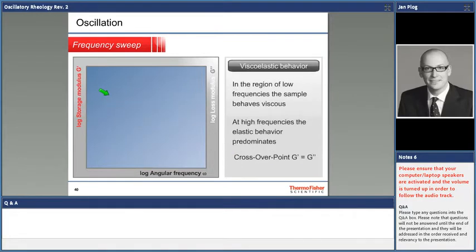However, those were the two extremes. Let's have a look at viscoelastic response. Okay, and here you see what I was talking about earlier when we talked about time scale. Every viscoelastic fluid, any polymer solution, any polymer-stabilized suspension or emulsion or whatsoever, or polymer melt, will show this behavior more or less, meaning nothing else than that at low characteristic speeds, your viscous behavior overcompensates the elastic behavior.